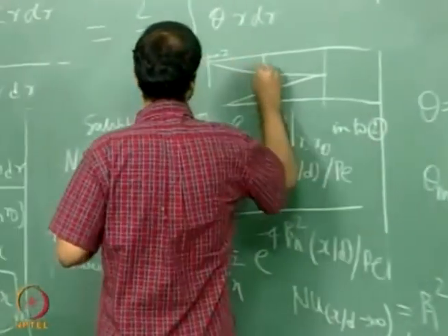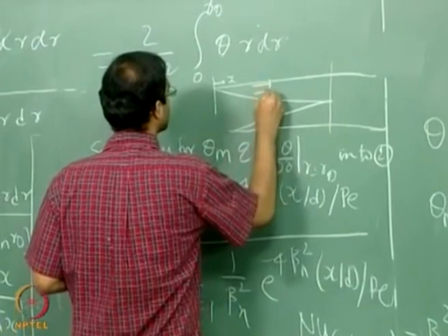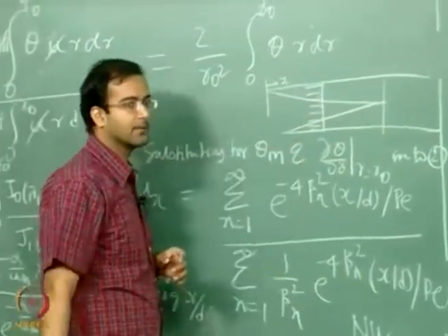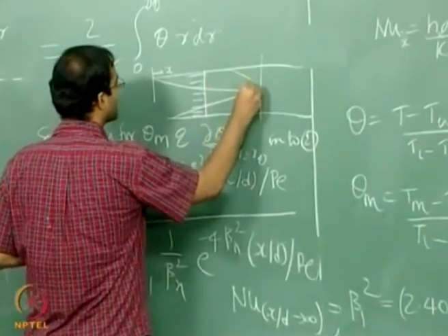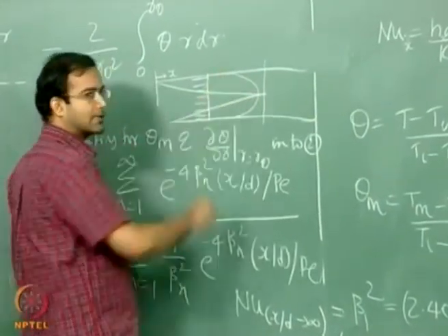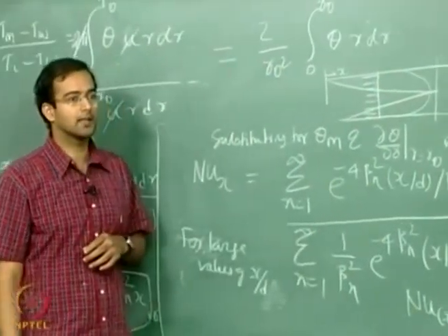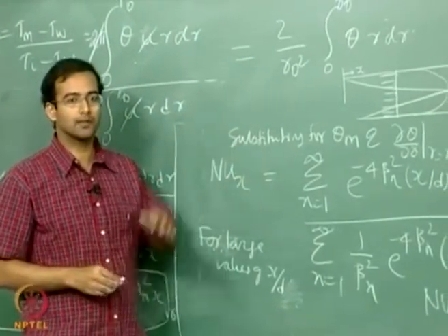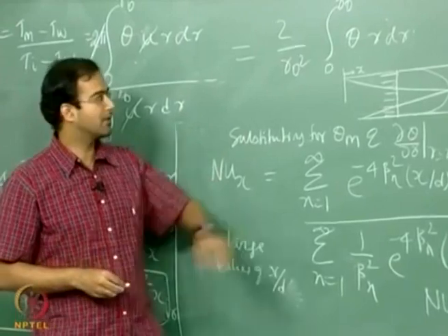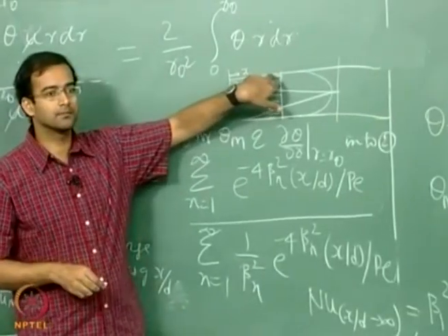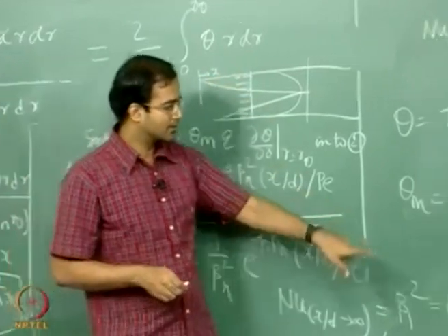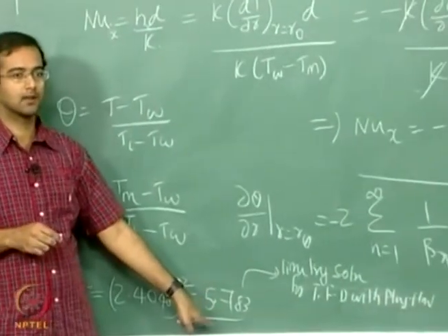So what is the significance of a uniform profile? Earlier when you had a parabolic profile, near the wall the velocities were small, so due to that the heat transfer coefficient is smaller. Now when you replace that with the uniform plug flow profile, the velocities are very high near the wall, and this will improve the convective heat transfer. So therefore you see the Nusselt number has gone up like anything.